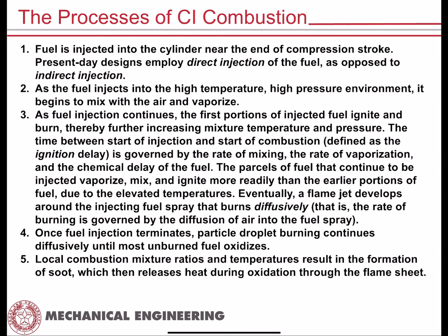So as we've already mentioned, first of all, fuel is injected into the cylinder near the end of compression. Modernly we do that injection directly into the cylinder. There's some engine designs out there, I used to say old style designs, that would do what we call indirect injection, and this is sometimes referred to as a pre-chamber. This is a means to ignite fuels that are difficult to ignite in very lean environments.